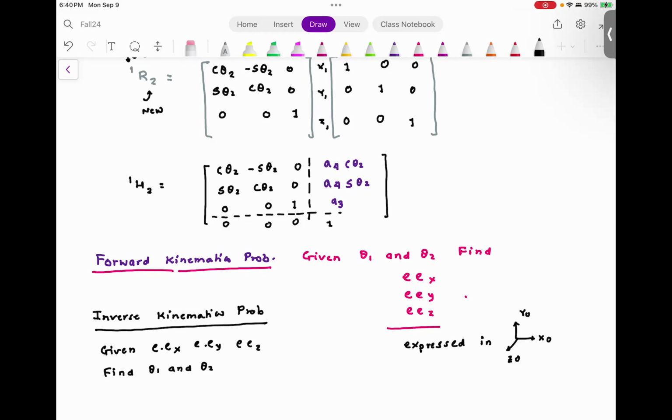Now here is the major problem. Look at the pendulum problem that we are trying to solve. So we have 2 pendulums, and if I give you an end effector position, say this is my first coordinate frame, and if this is my end effector position, this can be reached by these 2 angles, which means I can have maybe theta 1, and then I can have like theta 2, or the same end effector position.